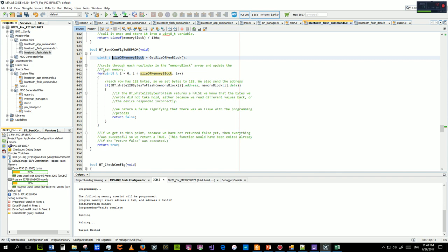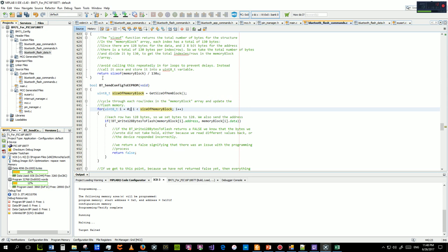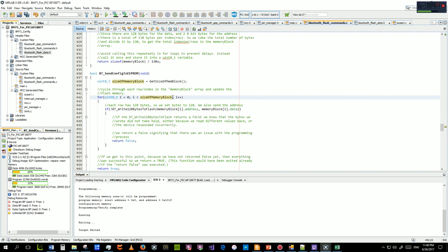So now we start going through the memory block. Now, here's something to understand. When we've already erased the memory block before we perform this operation, everything's already been set to 0xFF. So that means that all the empty memory that we're not dealing with, that doesn't have data, is already set to 0xFF. We don't have to do anything with that data. It's already been wiped out. All we have to do is write the new data, or the actual data that we want that's not erased.